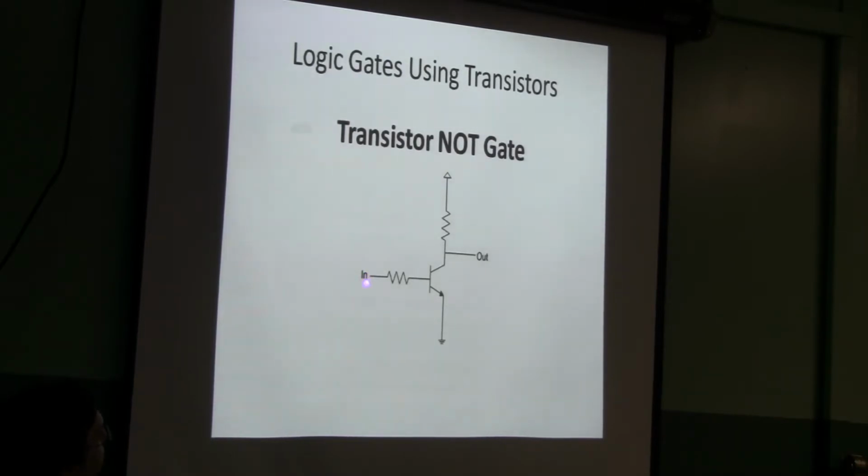This is another illustration of a NOT gate or an inverter. Whatever voltage you have, 0 volts on the input, you're going to have 5 volts on the output, assuming that this is going to 5 volts. We're going to probably talk about 0 to 5 volts because that's a very common voltage with computer circuits. So if there is 5 volts here, that turns this transistor on. And so then this will basically be connected from this point to this point, collector to emitter. And so the output will be ground. So this is on, this is off. This is off, this is on.